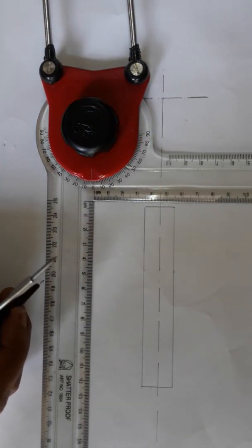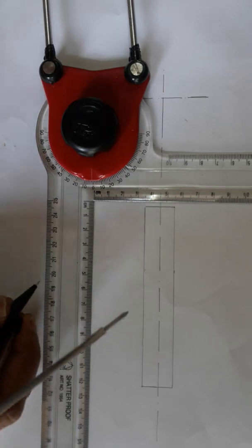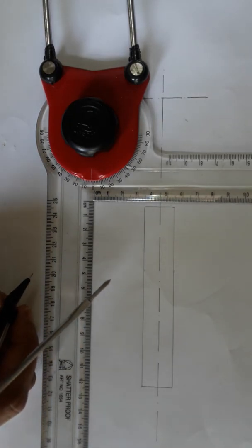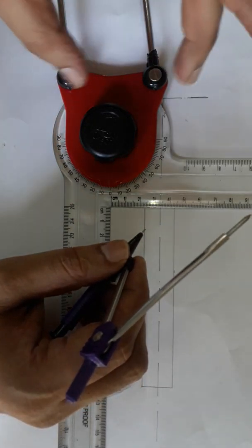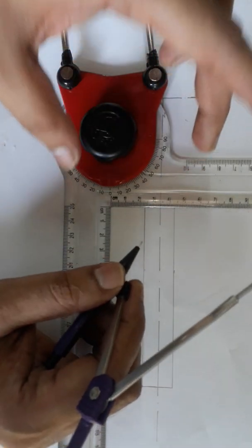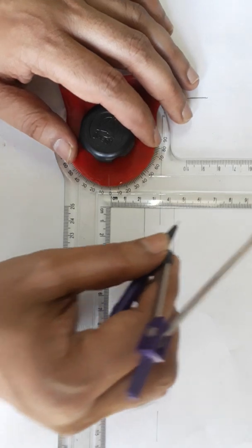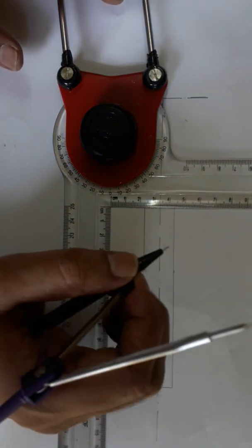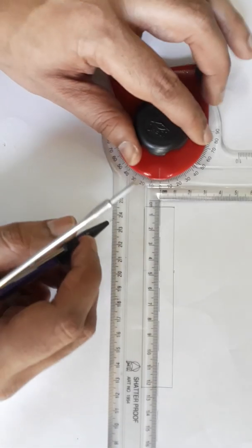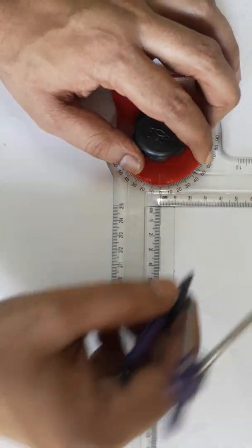Since we are viewing across the flat, the width of the flat we got is 1.5D plus 3 mm. Either you can draw the side view and project it, or you can directly draw the width of the bolt head, because we calculated the dimension as 38 mm. So 19 mm above and 19 mm below.